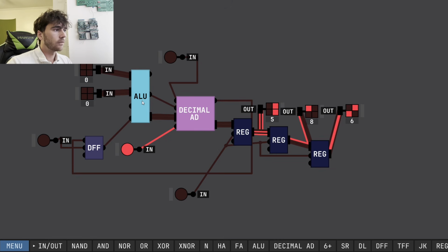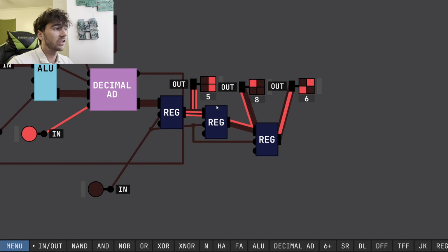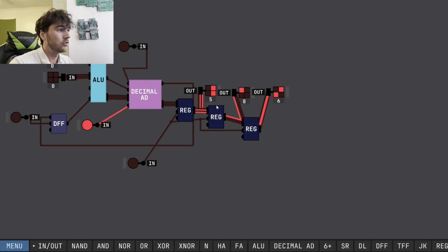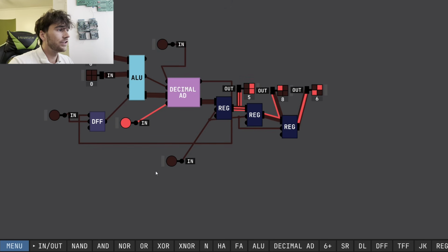But since the 4004 was never meant to display on a monitor, which uses millions of pixels, it was only meant to display on a piece of paper, which acted like a 7-segment display. And this is beautiful for a 7-segment display computer because all you can display on it can be represented with a single 4-bit number, and you just shift it per calculation. So that is how it would do math, which is one of the main things that differentiates it from other CPUs. It's this program counter, it's the way it does math, and the weird clock that we kind of see.